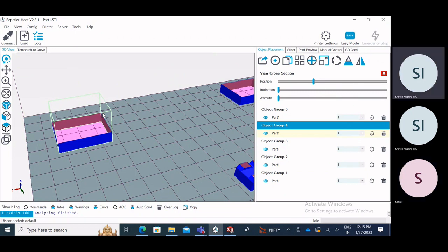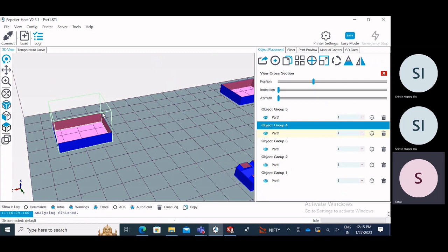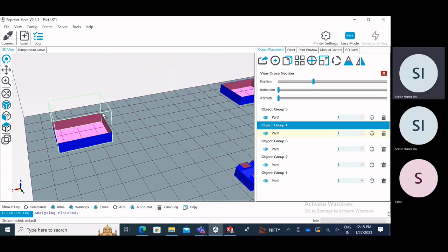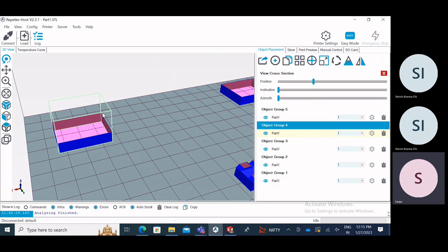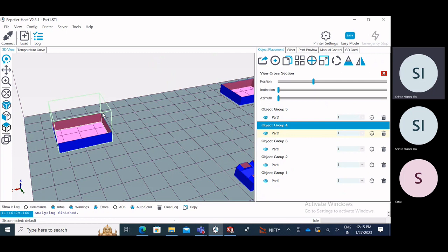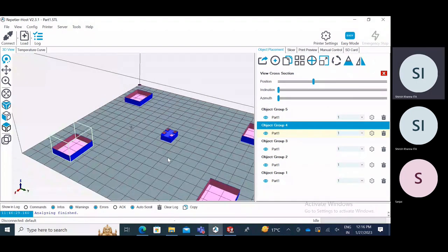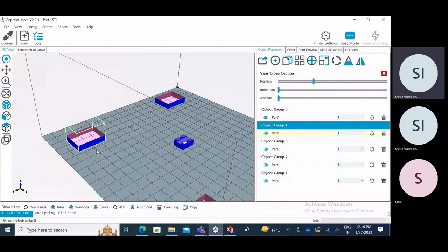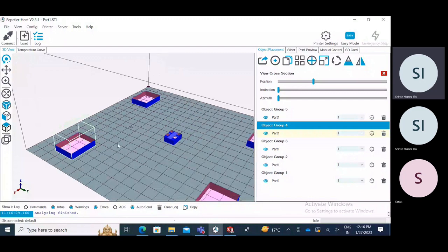If you want to create a solid material, we have to go for the printer settings first. So I tell you about the command first, then we go for the printer settings also, where we can see the inside shape. What we created in SolidWorks is a solid part, correct? This is a solid part. When it is converted into STL, it is converted into surface. If converted to STL, it automatically changes into hollow. Yes, it is a surface part now. Okay, it will create inside hollow, but if you want to give some extra material inside for the strength of the part, we can give that also. Suppose you want a grid shape inside, or a polygon shape, so many multiple shapes are also there. I can show you that also. When we are giving printer settings, then we can see that portion also.